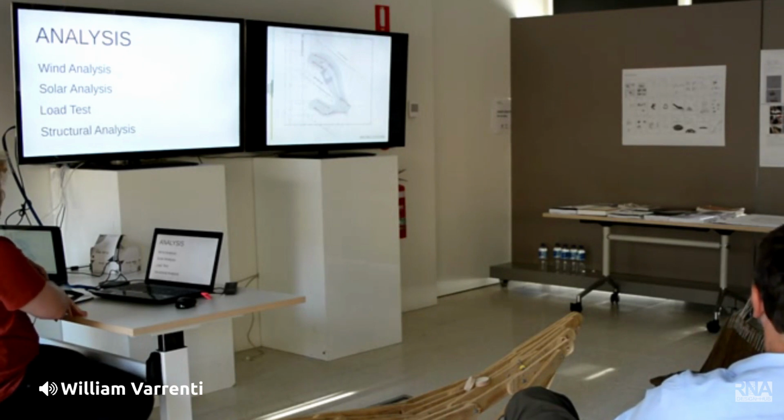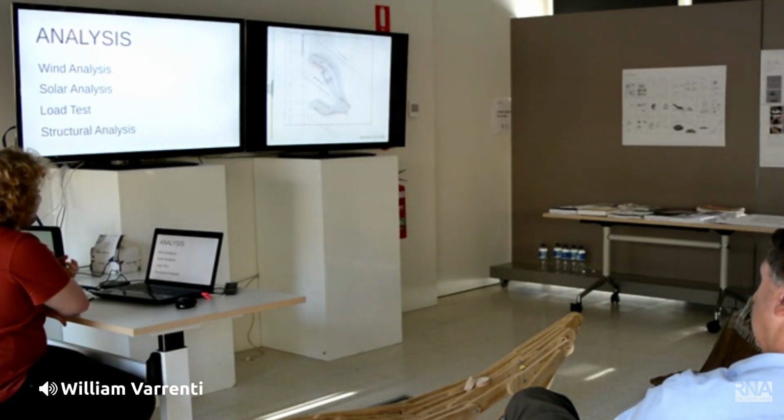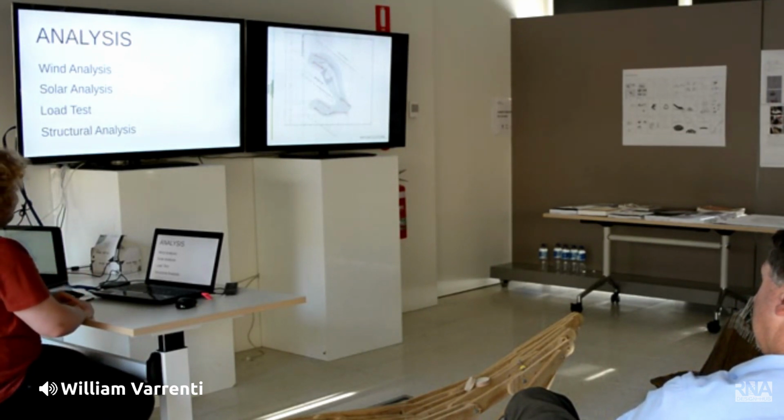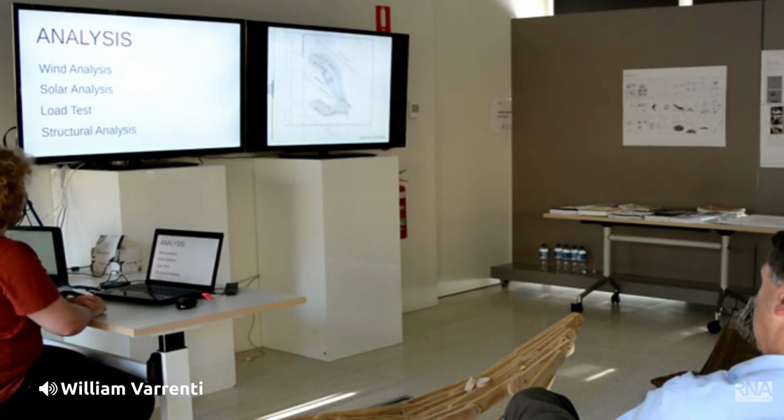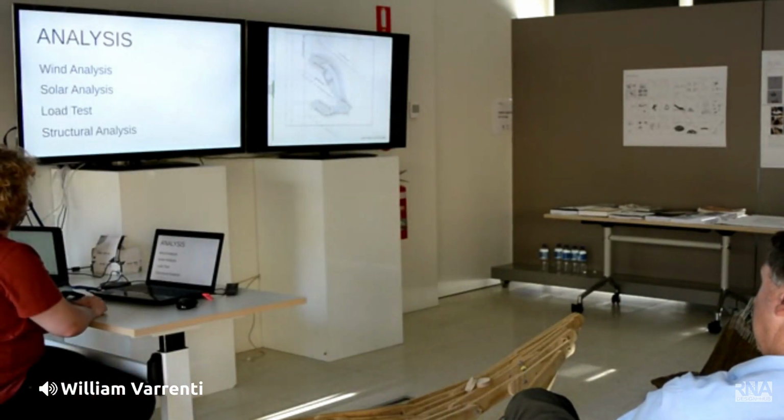And then looking at the physical prototypes, we noticed there was some warping, and the engineer determined that we should utilize some cross-bracing. So basically on the non-moving elements, we implemented steel cable cross-bracing to ensure no lateral movement.